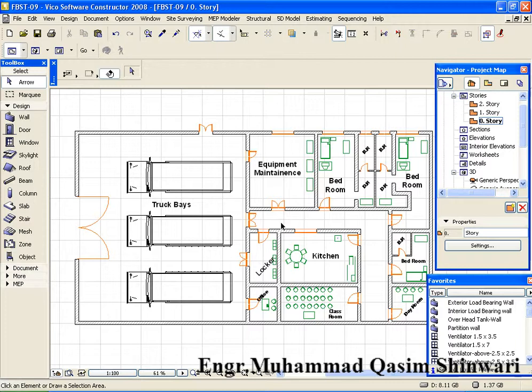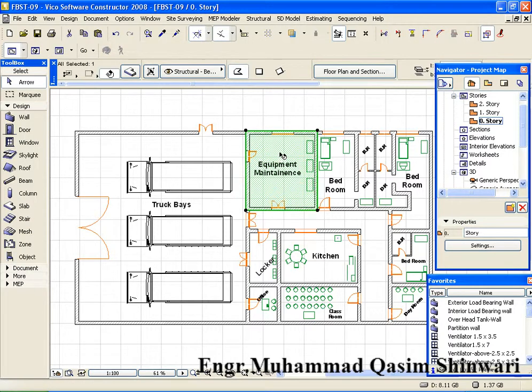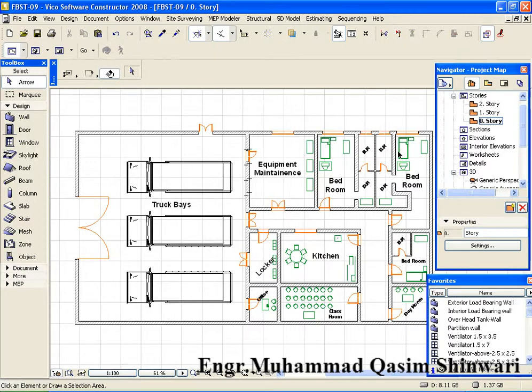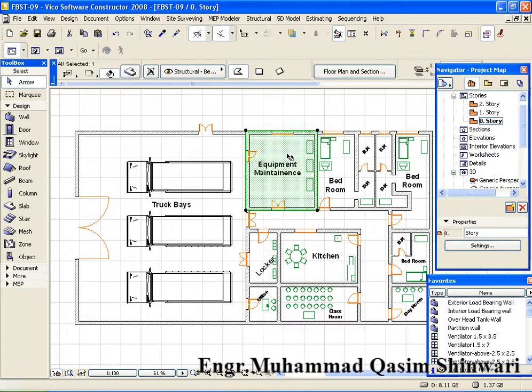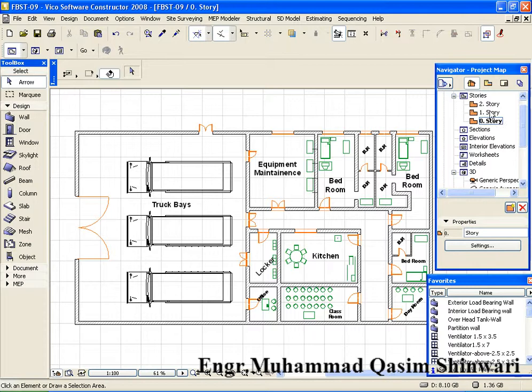There are many methods. First, the simplest method you can see is to define the favorite. Another method is to select the pre-constructed slab, shift select it and copy it, Control C, or right click in the context menu, then copy. Now go to the second story and press Control V. Right click, copy to make sure that it is copied.